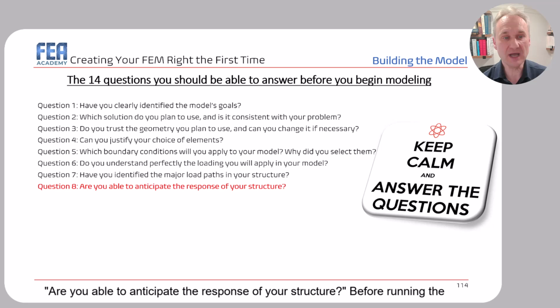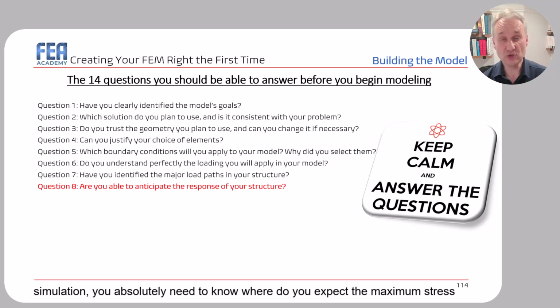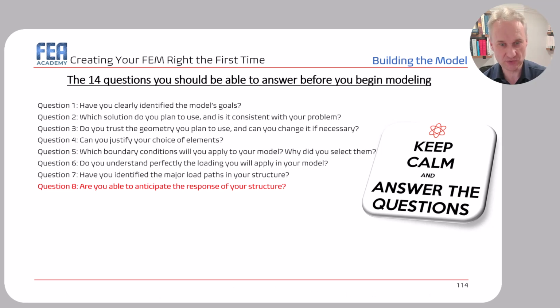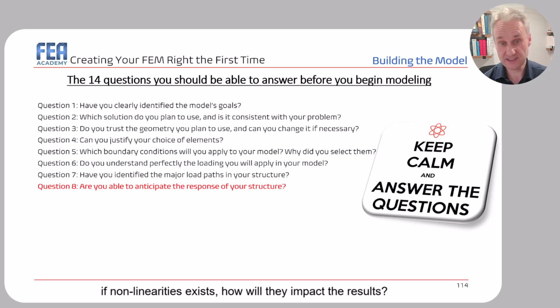Are you able to anticipate the response of your structure? Before running the simulation, you absolutely need to know where you expect the maximum stress or the maximum displacement. Okay? Will there be buckling or yielding issues? And if nonlinearities exist, how will they impact the result? Okay?